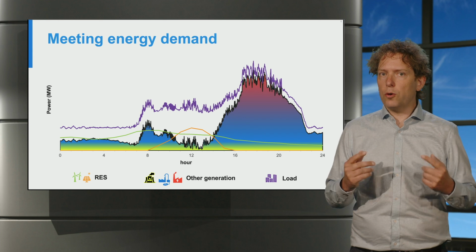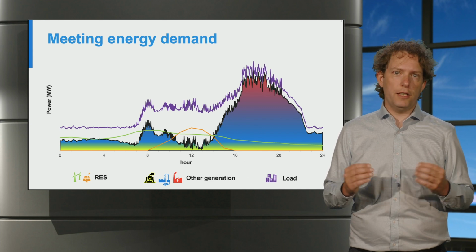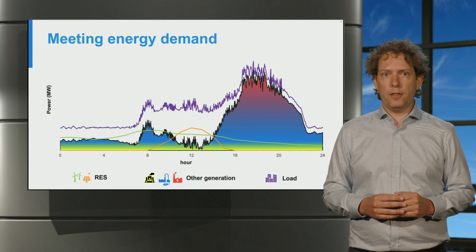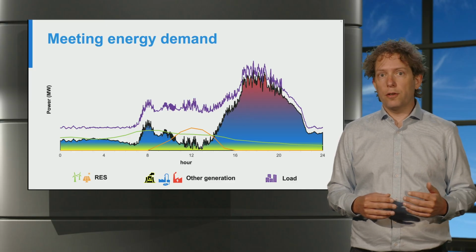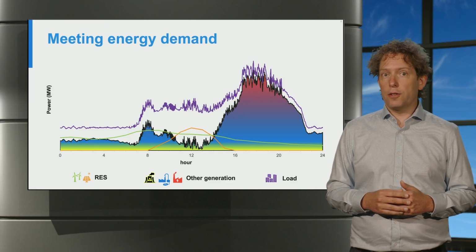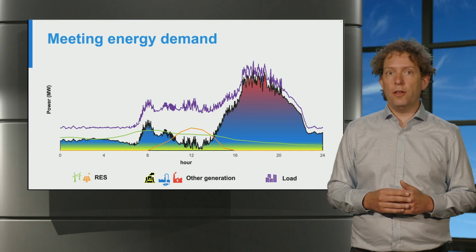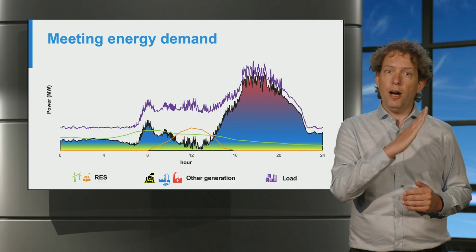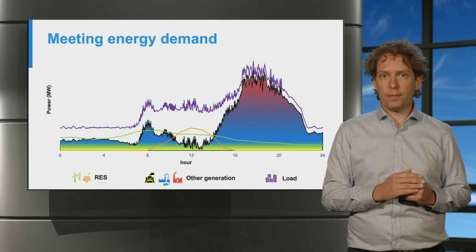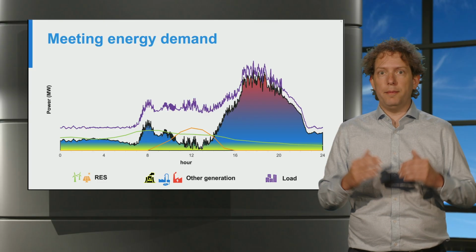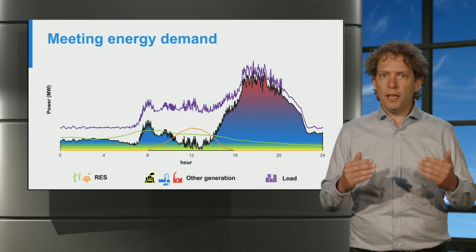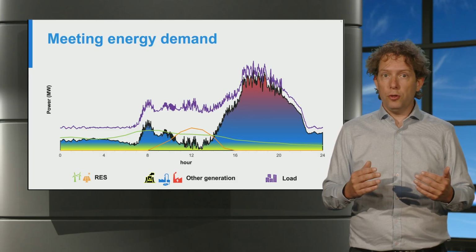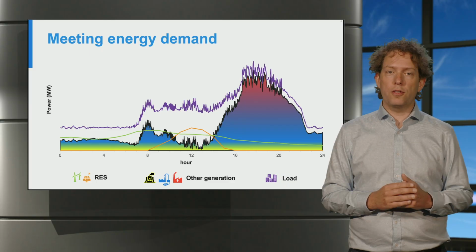But this picture also illustrates a fundamental challenge in renewable energy systems. The presence of solar power generation can result in extremely low remaining demand during the midday hours, followed by a very steep ramp up to a high evening peak. Now, if you recall the ramp limits on generators, this might really impact your ability to use low-cost or low-emission sources of energy.